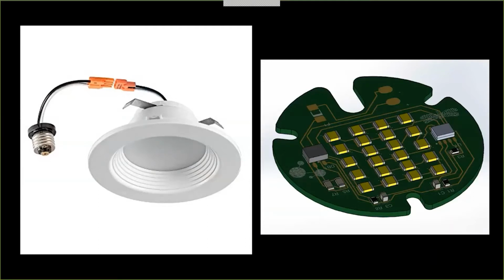So Mark Talbot, our PCB engineer, or electrical engineer, designed this board up. We used 22 LEDs and an LED driver, but a constant current source. And we modeled it up the first time. We said, let's use a green circuit board like most circuit boards you see. It's FR4. It's layers of fiberglass and copper.